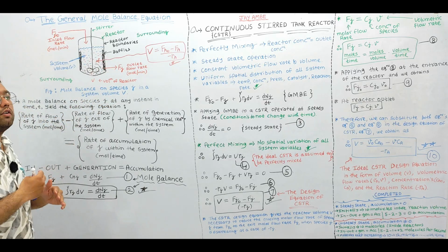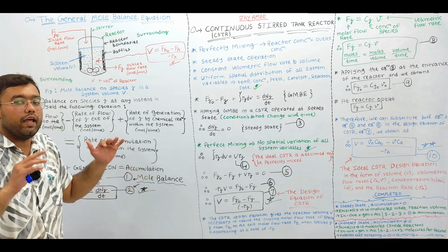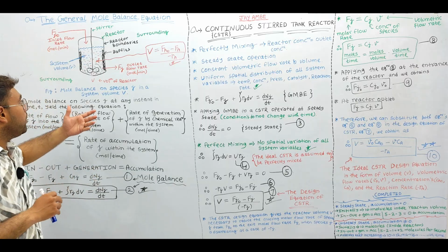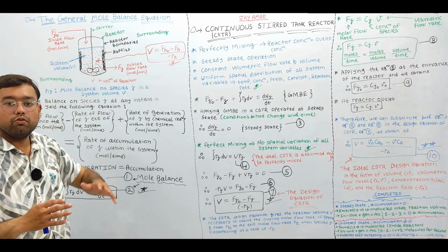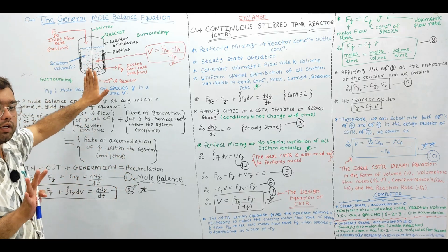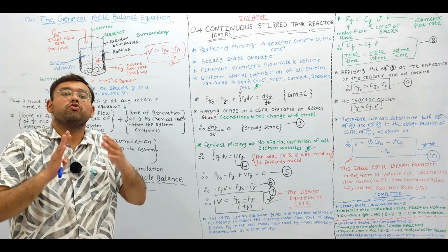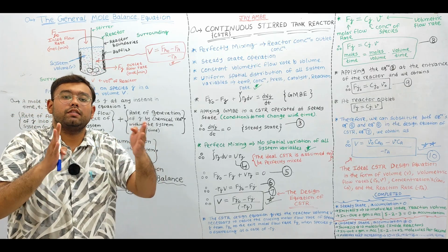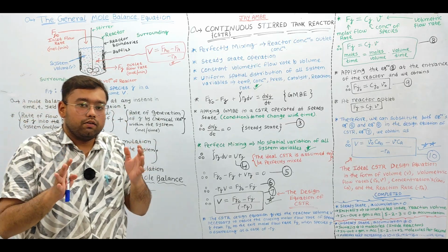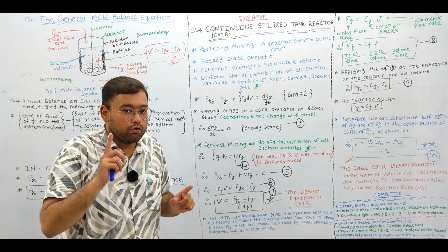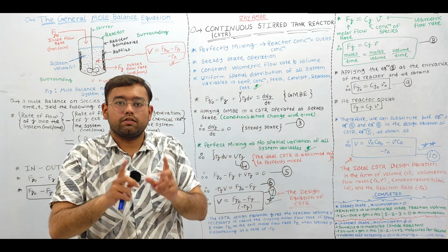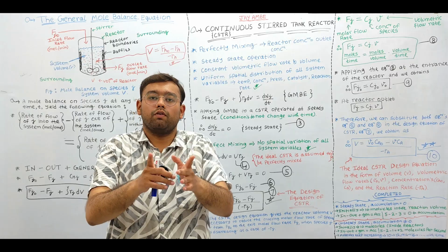And let's say after 1 month or 2 months, if we analyze the reaction environment, if we are continuously operating the CSTR, then we will have the same 10 molecules present inside the reaction environment, right? So there is no change with respect to time, which means steady state. The overall behavior of the reactor is constant with respect to time. So there are no changes with respect to time, which implies the steady state operation, the steady state condition where the accumulation term is equal to 0.